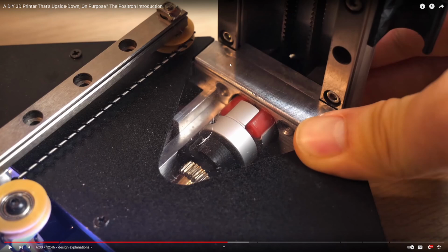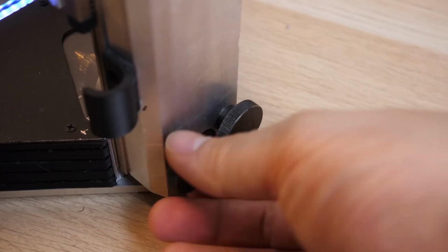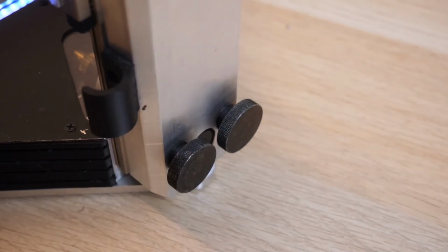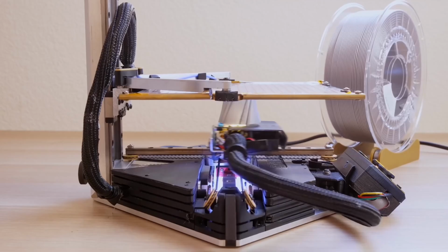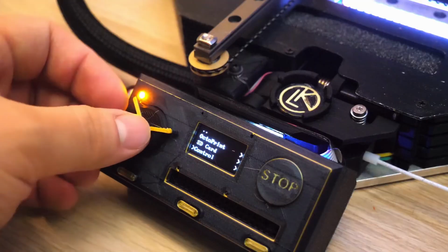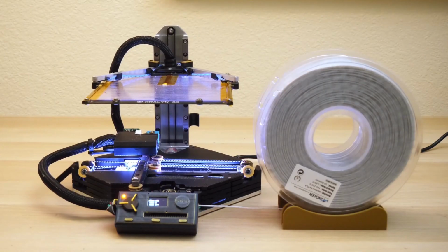And he has this exact precision block here that will tie in the vertical rods into the printer so that you can take it apart. It doesn't actually fold. You unbolt it and put it forward, and then you rebolt it again. Matches up with the grooves created by the linear rails on the Z-axis tower. This makes it so that every time the Z-axis will be always matched up perfectly straight and perpendicular to the printer body.